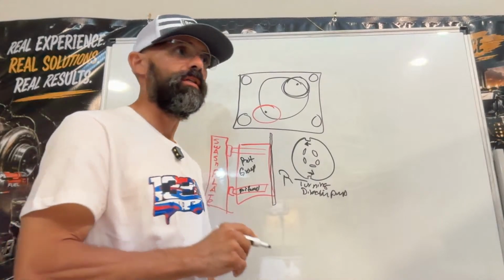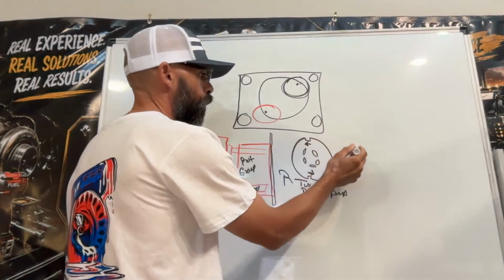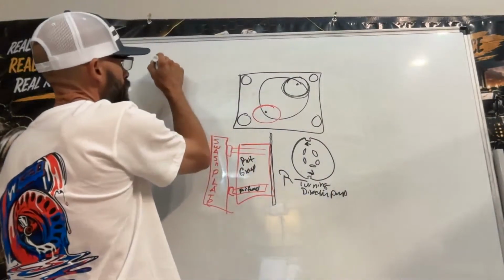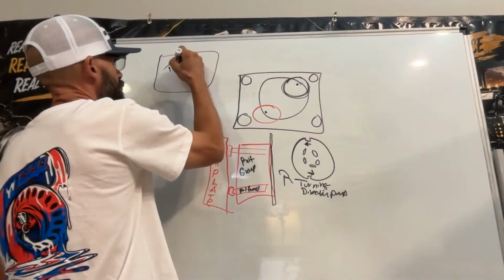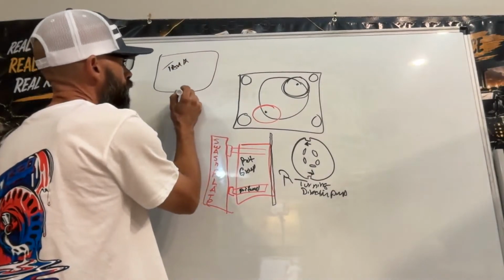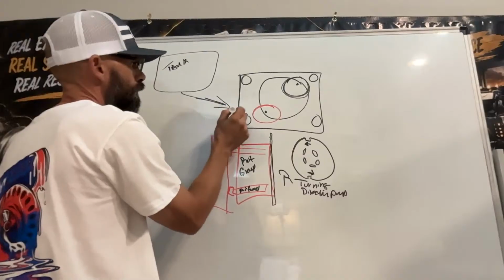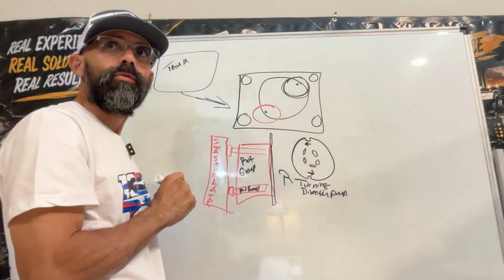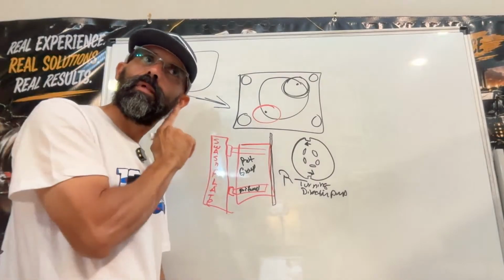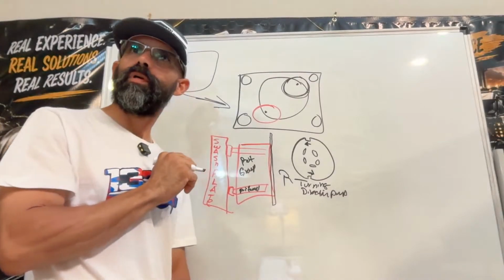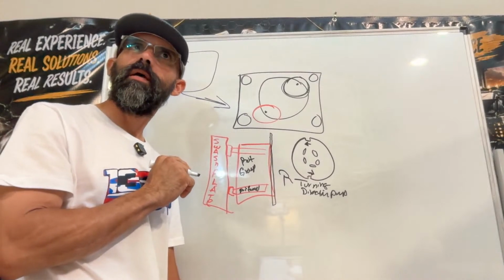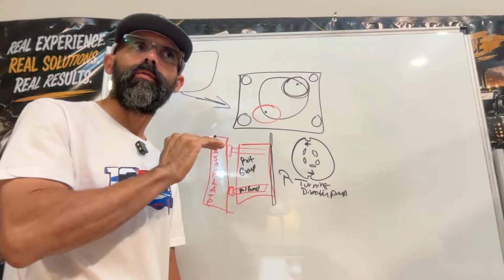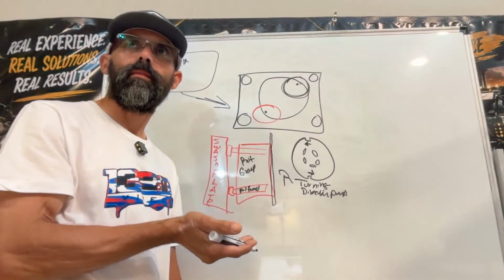Because if you change it, instead of the pump pulling oil from the tank, it's pulling oil from the pump. It might be doing something different, and you're gonna be hearing a weird noise and be like, why don't I have pressure? Why is the system not working or not reacting? Because there's something that was probably installed incorrectly.